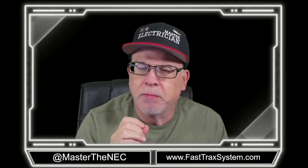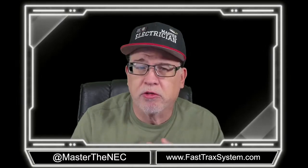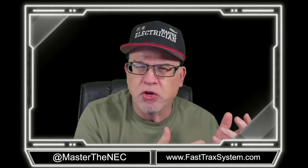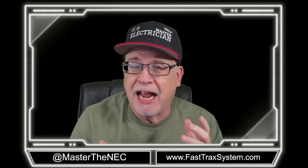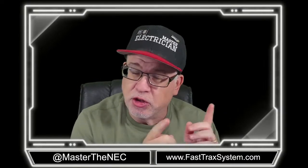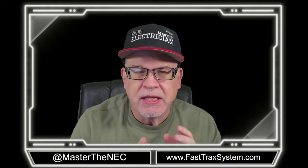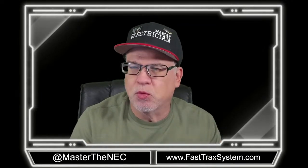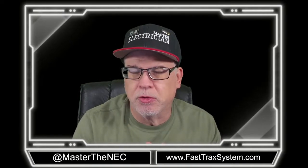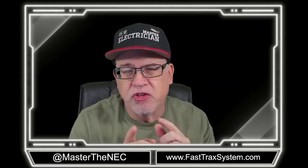The reason is, in part 1, we talk about what a neutral conductor is, what a neutral point is, what a grounded conductor is, and what creates a grounded conductor that is not always a neutral, but is always a grounded conductor, based on where that conductor is connected in the transformer at the neutral point. We also talked about how this was created in the 2008 edition of the National Electrical Code, so what we might enjoy today in the 2023 edition wasn't always the case. Clarity had to come from a task group back in 2008. So I want to make sure you go back and watch part 1 before you jump into part 2.